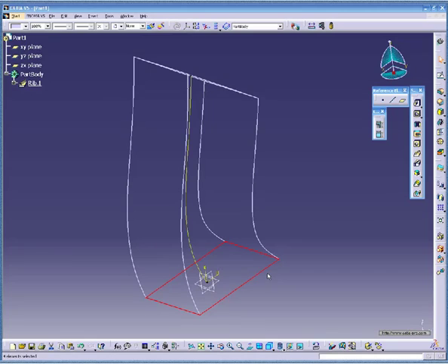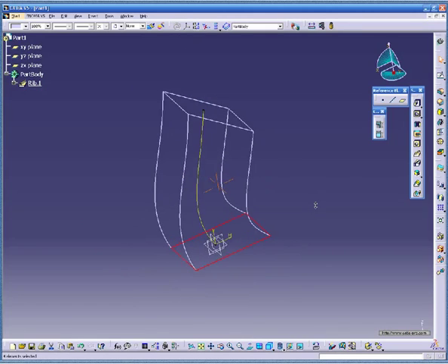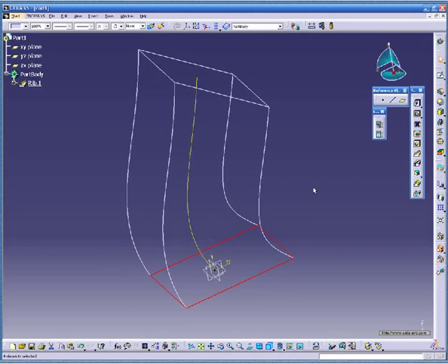Then we need to have first a 2D element called profile, which should be swept out on another 2D geometry called guide curve. And by that, the application will find the external boundaries for the 3D element. Consequently, extra operations will be done to find the faces and edges, and also the vertices that relate to the produced geometry. Then, let's see how to work it out.